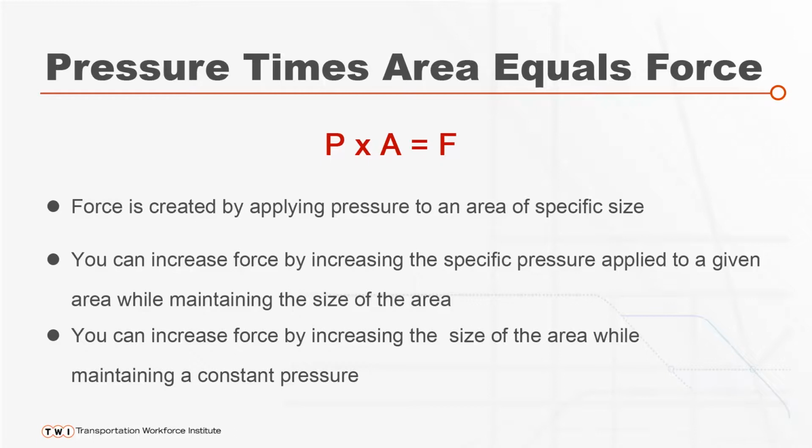At this point, I always like to reference things like door motors so you get a better understanding. You'll notice in a pressure differential motor, there are two different size pistons, and the way they work is we send the same pressure, say for round numbers 100 psi, to an area that has a given dimension of 2 square inches. 2 square inches times 100 psi is going to give you 200 pounds of force.